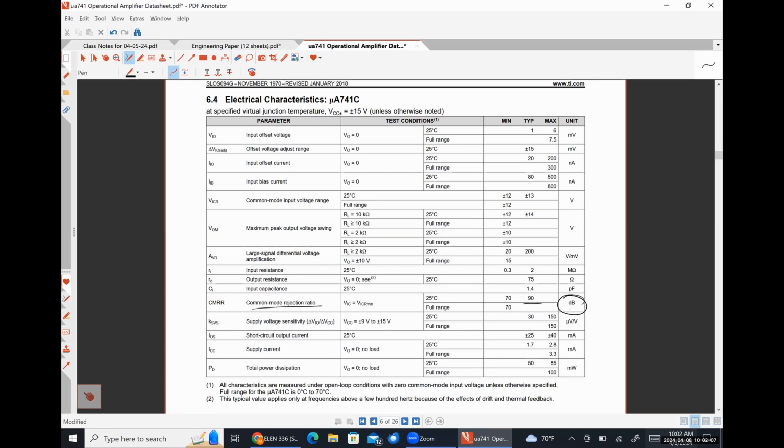So circuits can definitely be designed to provide a high amount of common mode rejection ratio, okay? Realistically, anything over 60 dB is fantastic. You're not really going to have to worry about things too terribly much. So it's just something to keep in the back of your head. There are always going to be manufacturing tolerance issues with any integrated circuit that you ever design or purchase. So having some understanding of what the common mode rejection ratio is will tell you how much those imperfections are going to influence the overall behavior of your system.